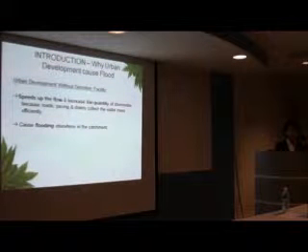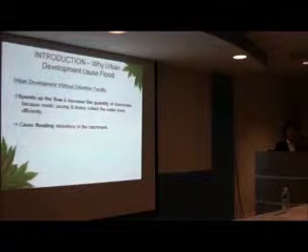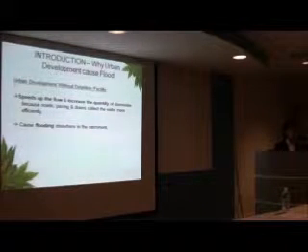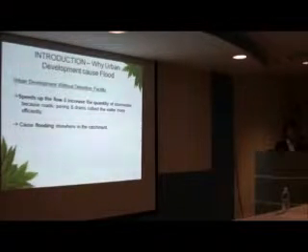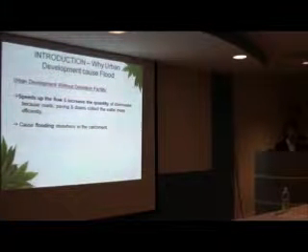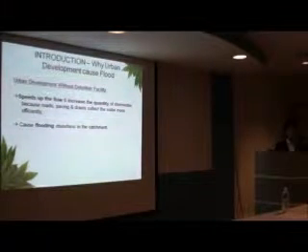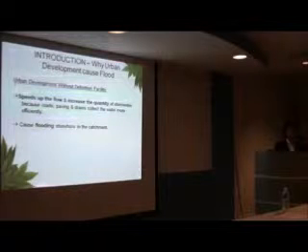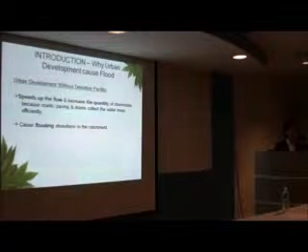If that development is without detention facility, those two impacts will speed up the flow and increase the quantity of stormwater because the roads, paving, and drains collect the water more efficiently. And the end result is flooding elsewhere in the catchment.